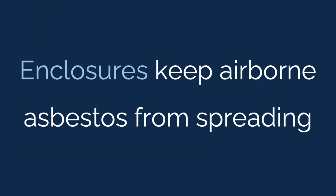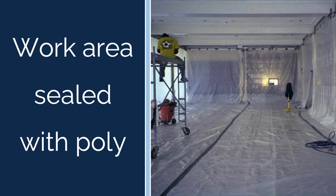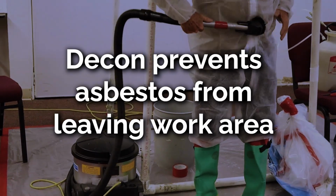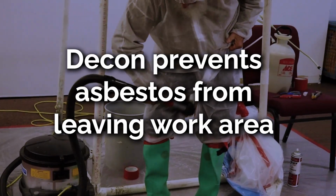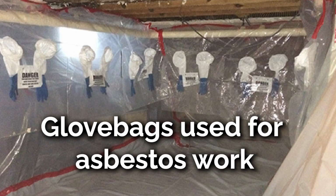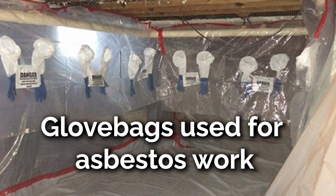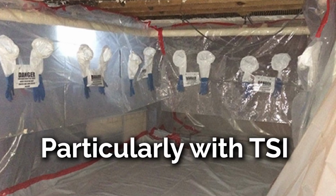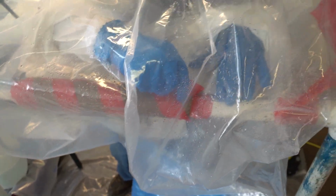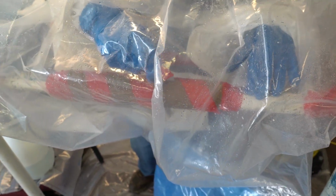Enclosure of the work area keeps airborne asbestos from spreading. This often involves sealing the entire work area in polyethylene sheets with curtained entry points designed to control airflow. Decontamination procedures for workers and equipment prevent asbestos from being carried out of the workspace. Enclosure and ventilation are usually used together. Glove bags are common tools for both small and large-scale asbestos work, particularly with thermal system insulation. Workers stand outside the glove bag and reach into the bag with attached gloves to do asbestos-related work.